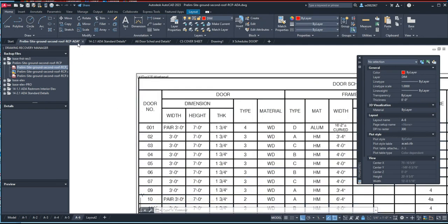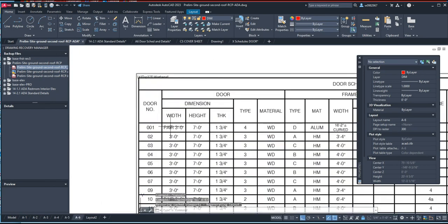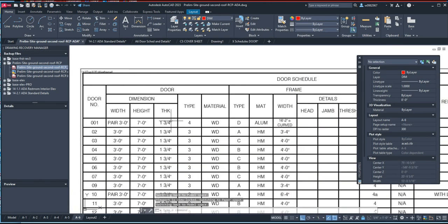So now if you go back again here to our A1, that's our main door. Each leaf is going to be 3/0 for ADA access. Because if this is closed, the person in a handicapped wheelchair doesn't need to open up the double doors just to enter. He or she can just open one of the doors, and that should be the case. That's for ADA. So going back to our A6 sheet, we're going to accept that pair of 3/0. And then, what's the door type?